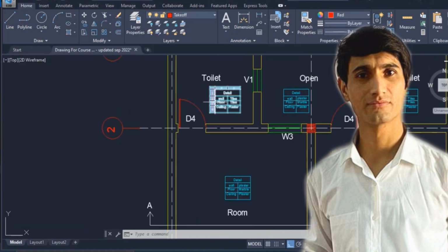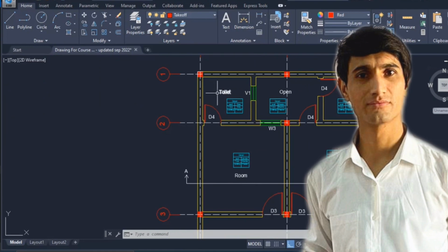So let me simply go here. This is basically toilet 1 and this is toilet 2. Now for the floor we need the total area for the tile, and for wall we need the total area for the tile. It is very important while finding tiles to check the internal elevation of the toilets as well, in order to check the total height for the tiles.